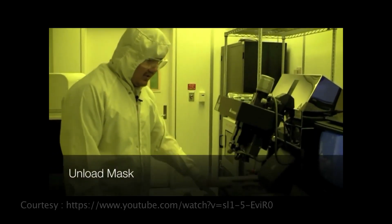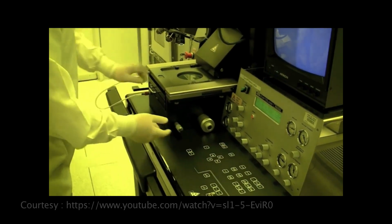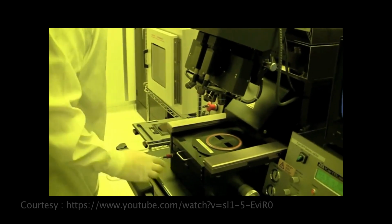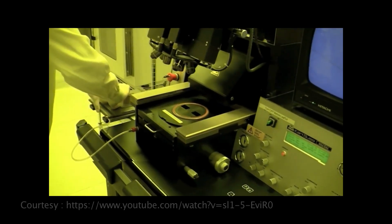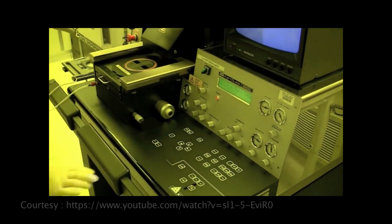If we want to unload a mask, we press the change mask. It's pretty similar to loading it. It's a reverse process. You would press change mask. You would take your substrate out. You would hit the enter button to remove the vacuum. And then you would take your mask out. You would press the change mask button again. And it would say confirm and enter, as you know the mask is there.